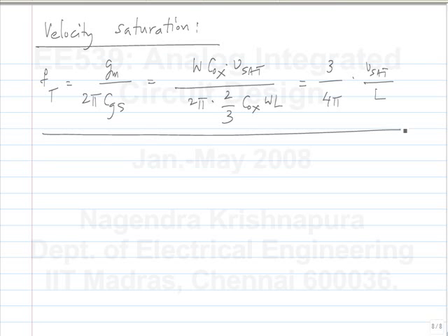So Ft is a measure of speed of a single device. Of course, when we make more complicated circuits, we can evaluate the frequency response and see what the bandwidth is that we can get and work out the trade-offs involved in increasing the bandwidth. But if you did not have anything else, just for evaluating a technology, you can use Ft as a measure of an individual device.